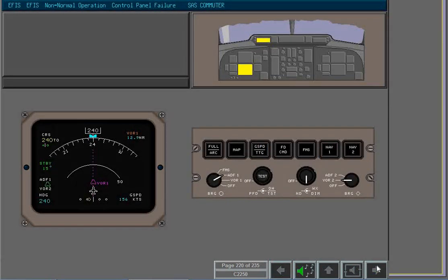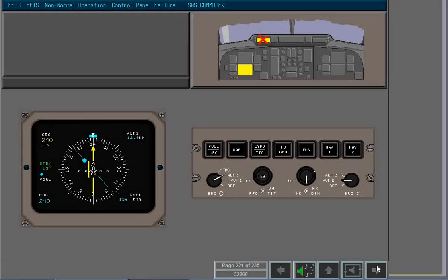During normal operation, selections at the EFIS control panel affect displays at the on-side display units. In the event of a left EFIS control panel failure, Symbol Generator 1 makes automatic selections for display. Current and further EFIS control panel settings are ignored.